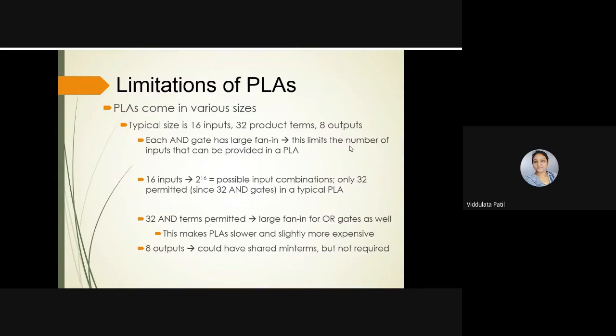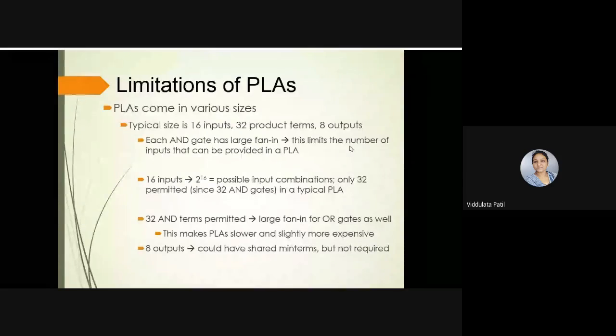Again, we have 8 outputs only. In a typical size, we have 8 outputs. So we could have shared min terms. Whatever the product terms are, we need to share them in a proper way in a PLA. So that is also one of the drawbacks of this PLA.